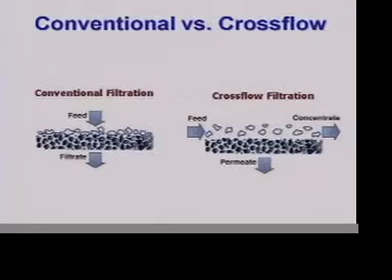On the other hand, the membrane technologies almost completely are based on cross-flow filtration. You have one stream coming in, carrying the contaminants you want to remove. This whole system is under pressure. So the pressure forces some of the purified, if you want to call it that, water through the medium, and this becomes the treated water.